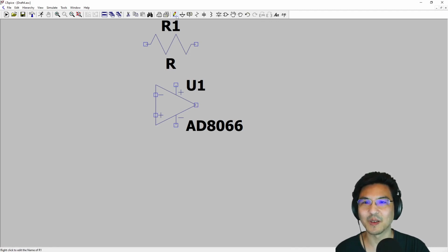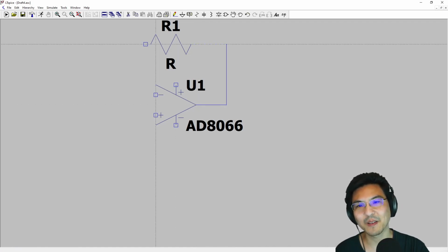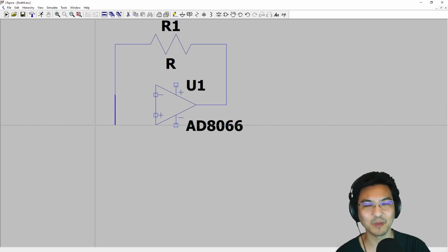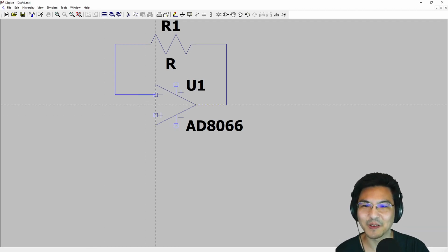Okay, now you can wire it, right here, wire. The output goes back through this resistor to the input. Which input? You're subtracting out error, right? So subtracting, minus, it goes to the inverting input, the one with the minus. So now we have an op amp with feedback.